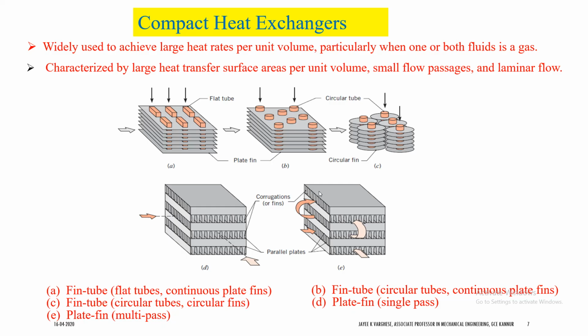That is more important. So here, in a heat exchanger, the heat is transferred by conduction and convection modes. Radiation will not be there in normal types of heat exchangers, so we are not discussing radiation. Still, in some cases radiation can be there. So if we assume that there is only convection and conduction mode, then the total heat transferred between the hot and the cold fluids can be given by Q equals U into A into delta T. It's as simple as it is.